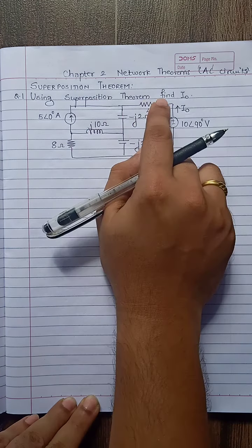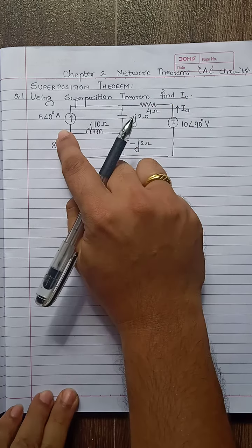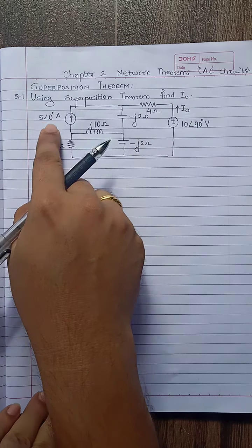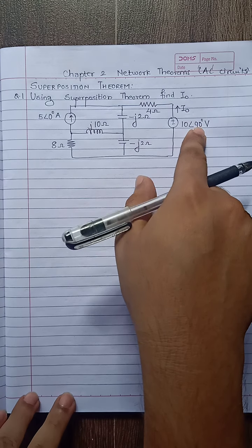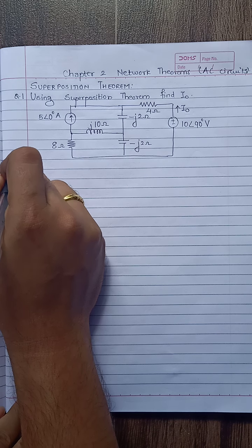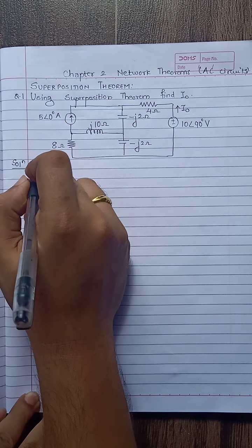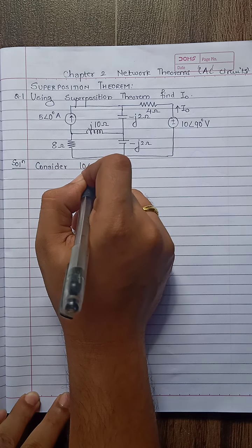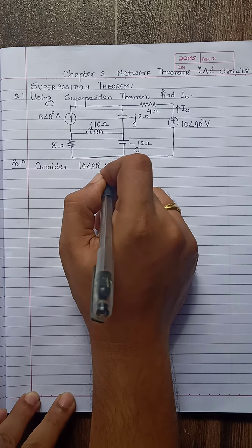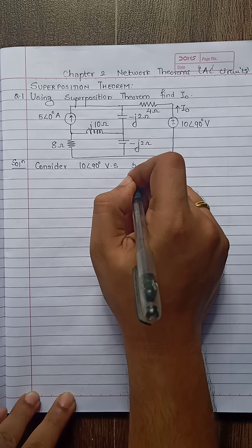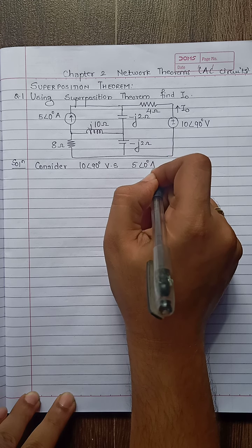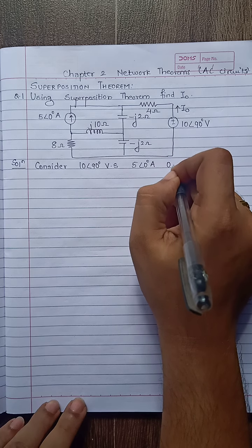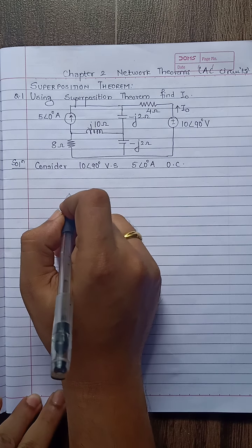So using superposition theorem we need to find the value of I naught. You have two sources, 5 at an angle 0 and 10 at an angle 90. So first I'll consider 10 at an angle 90 degree voltage source. So 5 at an angle 0 degree amperes will be open circuited. So the modified diagram will be